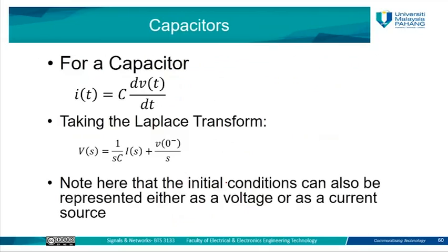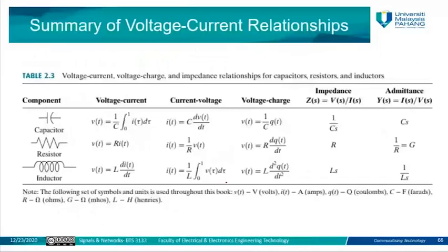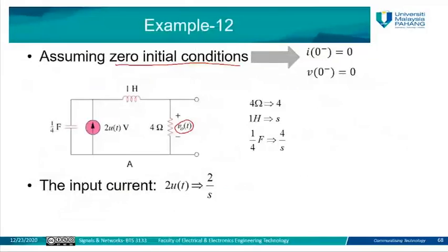So we only consider the values of the elements and the values of the voltage and current in our circuit. When it says the initial conditions are zero, that means all I0 equal zero and all V0 equal zero, so we do not consider them. The next step is to transform this circuit from the time domain to the frequency domain. How can we do that? We need to apply the formulas that we have for the elements inside the circuit and redraw the circuit with the new values. This makes it easier for you to analyze the circuit. You have this capacitor, for example.